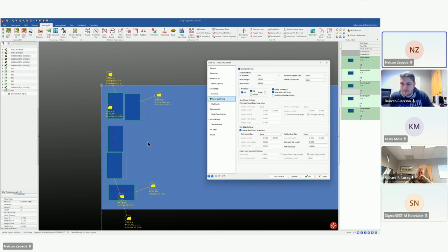So if you have a material recycler you work with, and everything they accept is smaller than 4x4 or 2x2, whatever the case is, you can cut your skeleton down to smaller pieces, so it's ready for the operators. They don't have to cut it up or handle it afterwards and add those cuts themselves. It's done through the NC program.